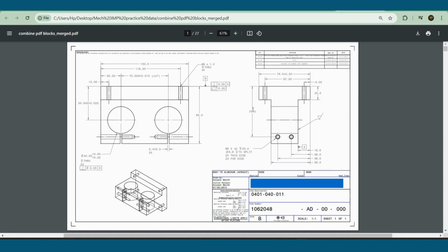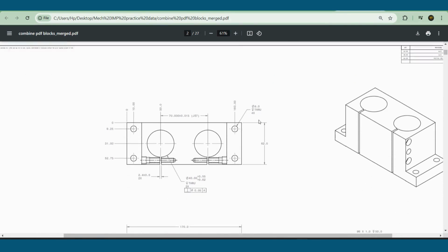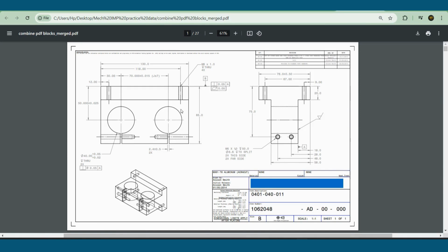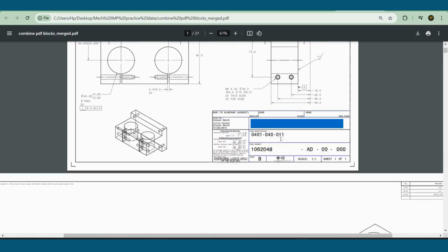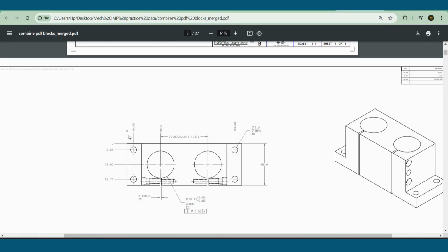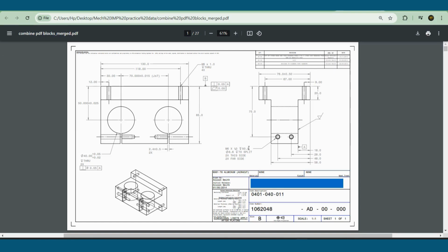To start with, I am having some drawings here you can see. In these drawings, we are going to learn how to apply smart dimensions, how to apply coordinate dimensions. You can see this coordinate dimension way, how to change the leader type and styles, how to change the precision of dimensioning, how to change the text size, and how to put dimension with trailing and without trailing zeros.